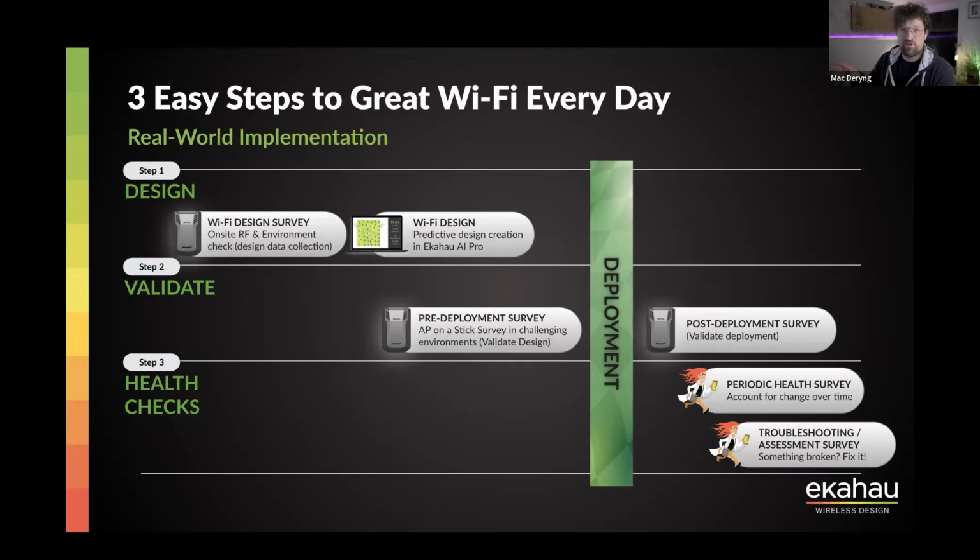Because if you assume wall attenuation that is incorrect in your design and it's vastly different, then your design might not work. And most importantly, or as importantly, you really want to understand the limitations of mounting your access points and antennas. Where are the preferred locations where you can and cannot run the cable? You can't do that just looking at the plan. So you need to go to the site, you need to take your measurement device, which will be a Sidekick 2, and you will do all of that I have mentioned.